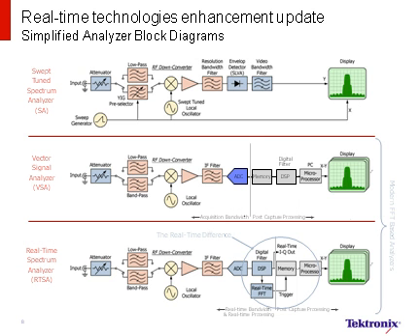The signal is passed through a resolution bandwidth filter, which limits the instantaneous bandwidth of the signal that can be viewed. A modern vector signal analyzer architecture is shown in the middle, and it converts the available spectrum using a stepped LO. The VSA then digitizes the wideband signal into the time domain and stores it into memory, converts it into the frequency domain, and displays the spectrum.